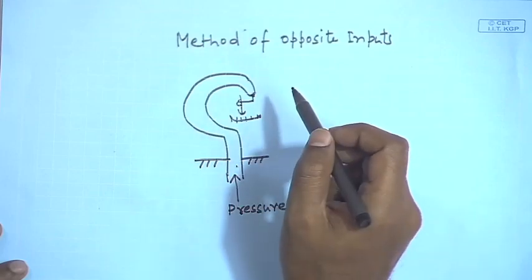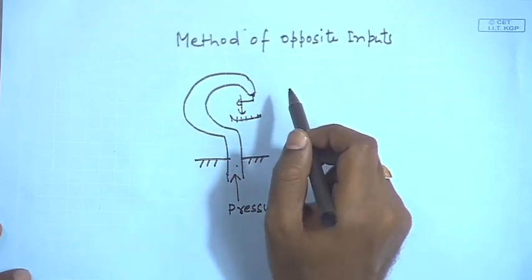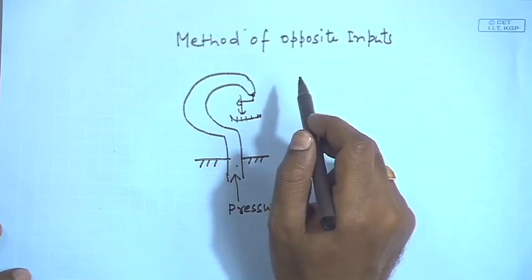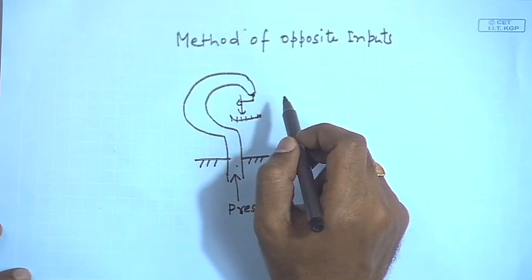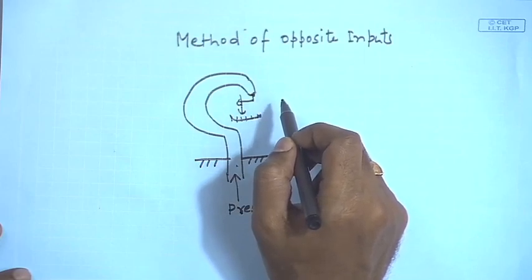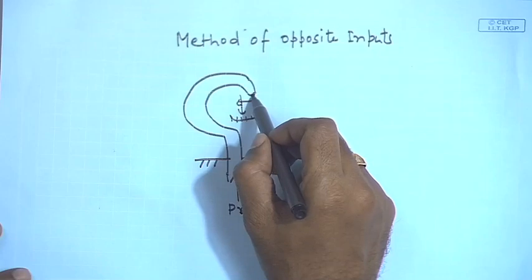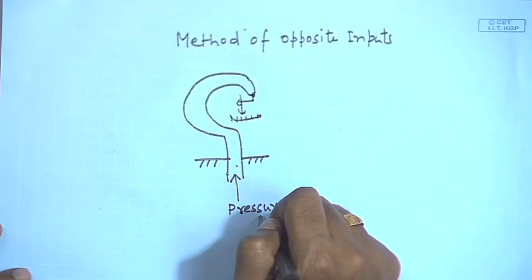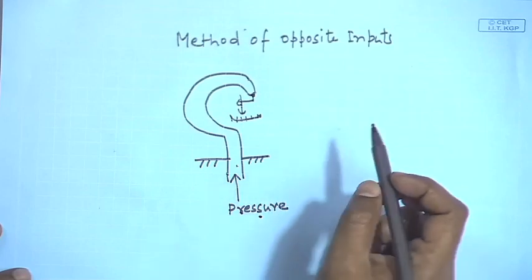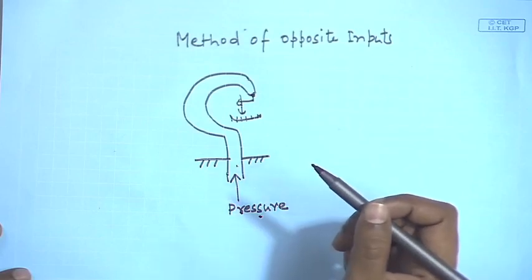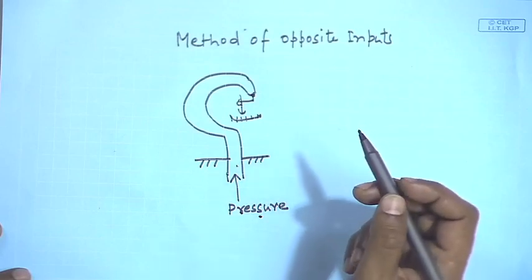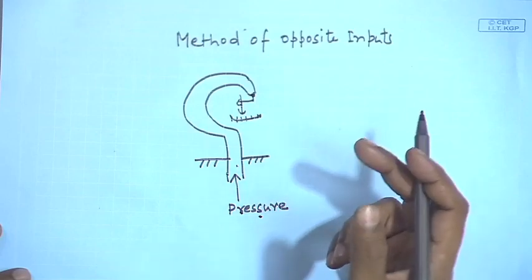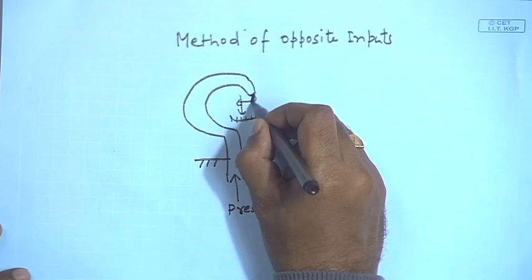So, modulus of elasticity can change with temperature. Now, if it changes sufficiently, the tip deflection can no longer be considered as a function of pressure alone. So, we can get additional deflection for changes in temperature. One solution can be, we put a bimetal strip here.